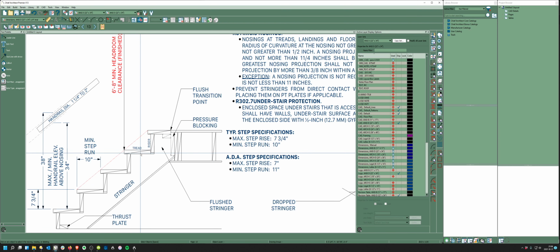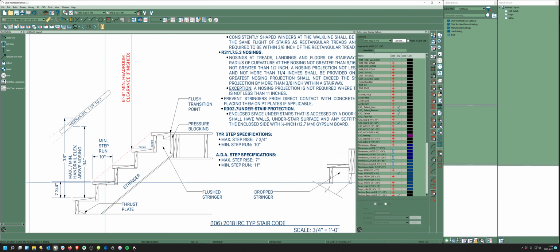A lot of guys will do just the stringer and put hardwood on top of just the stringers. What I like to do, if I know you're going to add 3/4 inch hardwood, is take 3/4 inch out of the bottom. I'll drop everything 3/4, and then I'll have this solid nailing surface.